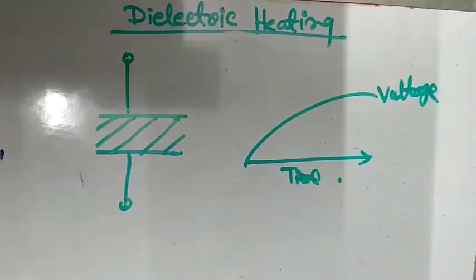As a result, the dielectric material will not be uniformly heated, and therefore it is important to choose a suitable frequency of supply so that standing waves are not formed. A safer and judicious solution will be to select a frequency such that there is a great difference between the electrode spacing and the quarter or half wavelengths. If it is not possible because of conditions imposed either by the load or the source, some other means like introduction of tuning stubs must be provided to avoid formation of standing waves.